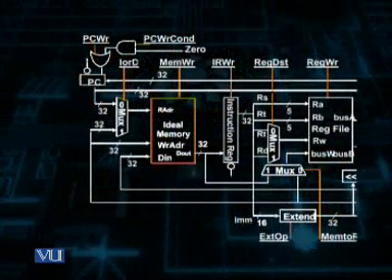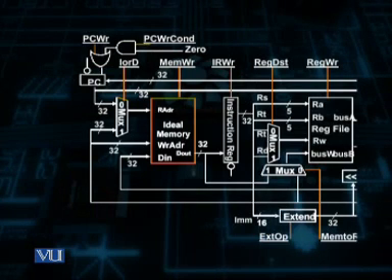These two registers, which are identified by RS and RT in the instruction word, are read in anticipation of whether they are to be used for an R-type instruction or for some other type of instruction.